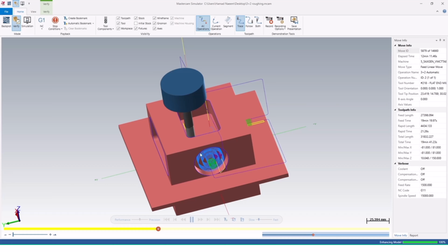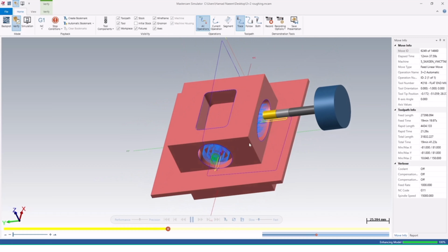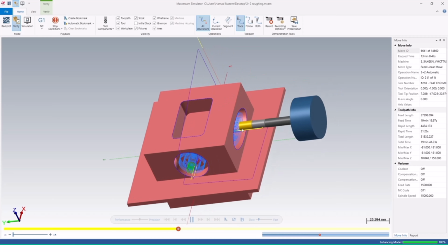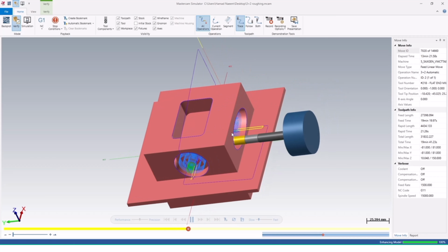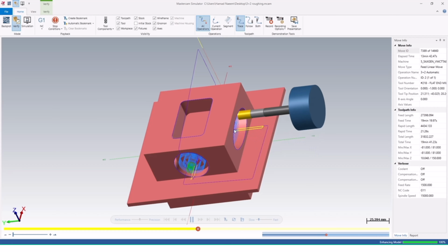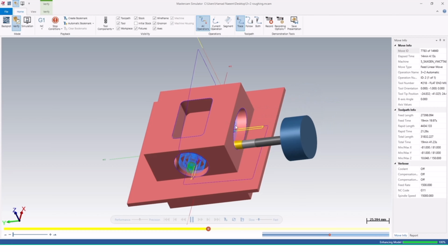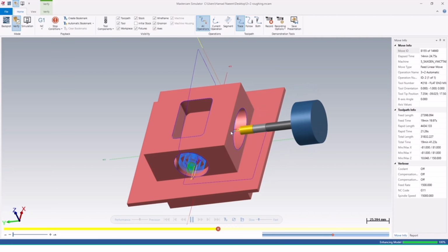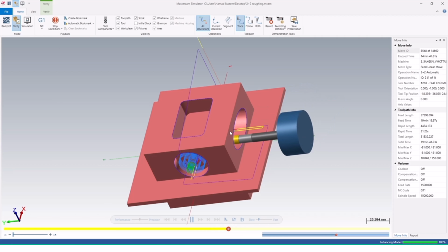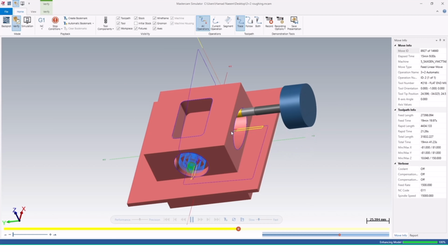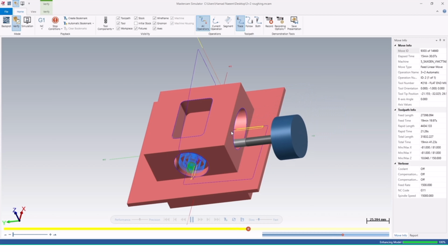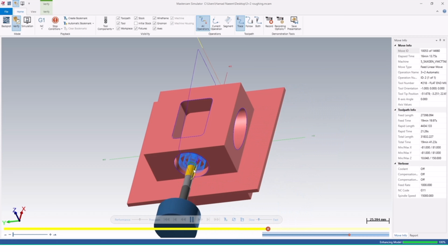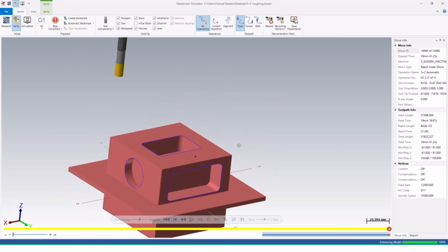It automatically defines the plane and defines where it should cut the material according to geometry. So it studies all the geometry first and then creates the planes and then sets the origins accordingly. And now on this side. So this is how the 3+2 roughing operation is done.